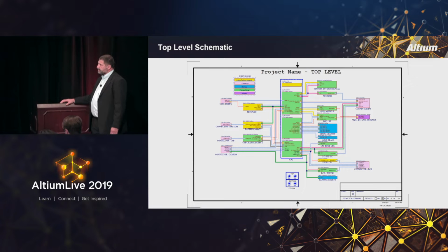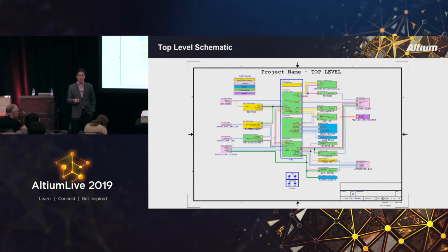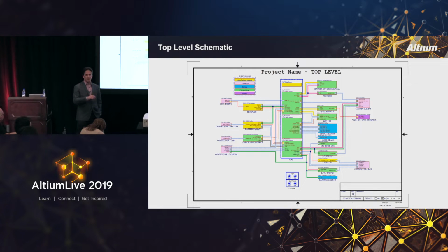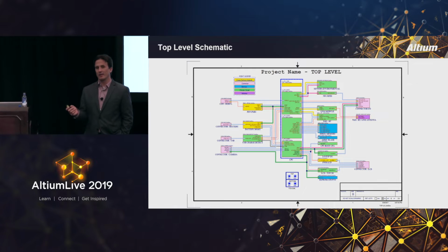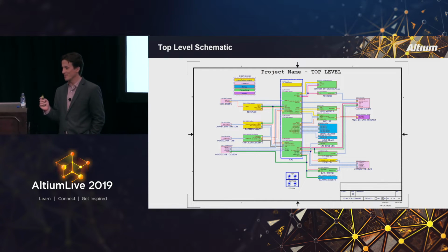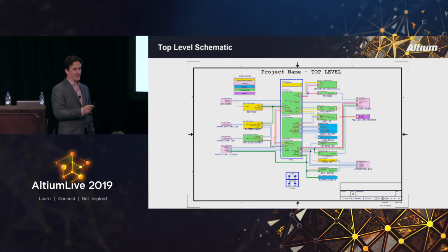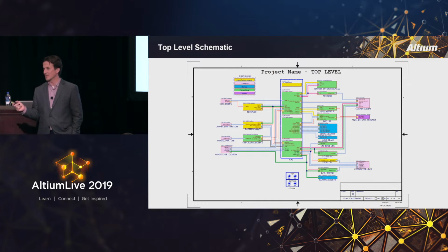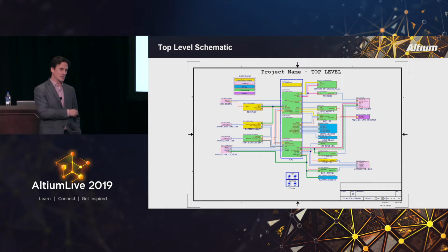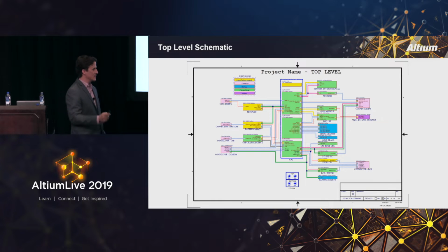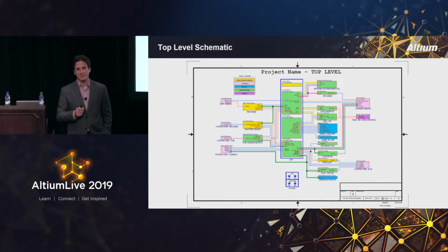Yeah, I've done this at one point in my career, and I've seen tons of engineers do it. They do their entire design, they go through prototyping, they verify functionality of the circuit, and then they think, I've got to do certain things to pass my regulatory compliance, and I'm just going to throw in these TVS diodes at the end, and it's an absolute recipe for disaster.